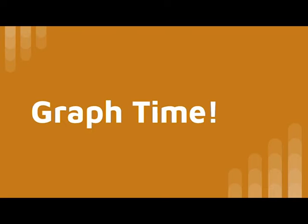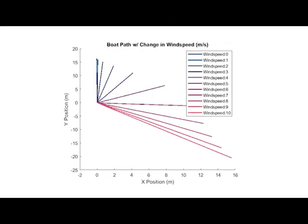Now then, what were the results from this simulation? So if you look, the first thing that we tried was varying the wind speed. As you can see, at very low wind speeds, the path of the boat was pretty much entirely up to the propeller. But as we increase wind speed more and more, as the wind speed is going to the right in this graph, we saw that not only does the boat push further and further to the right, but the force of the propeller is actually counteracted by the Magnus force, as the Magnus force pulls it back down